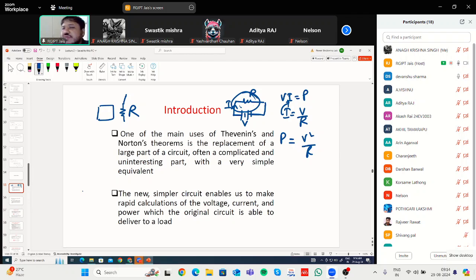Okay, we will see in your future, you will understand how these things function. So whenever there is magnetic fields in a particular appliance, this inductor comes into picture. So that load where there is some kind of a magnetic field, you cannot simply represent it by R. R and L both will be required. And here complication comes. Whenever the load has inductor or capacitive things, complications come. That we will study in AC circuit.